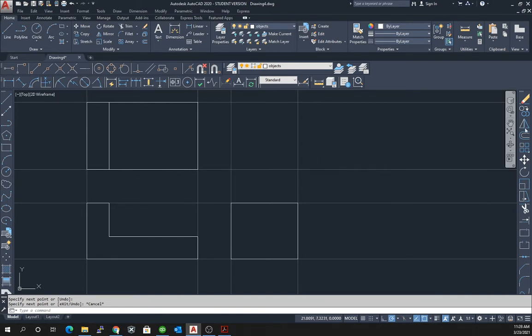And in fact, again, we can use offset. So we choose offset. We're still at 1. So we can choose this line. Choose offset. Select 1. Choose this line and move it up. And then choose this line and move it up again. And that actually gives us the proper line here, and it starts this opening here.